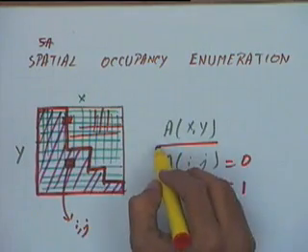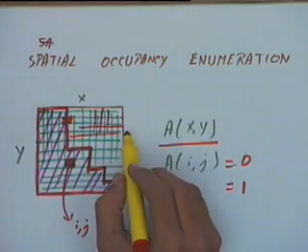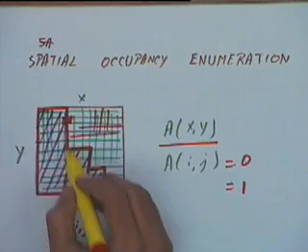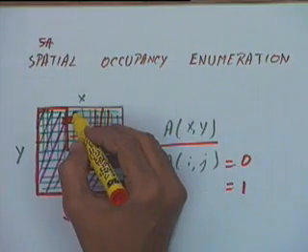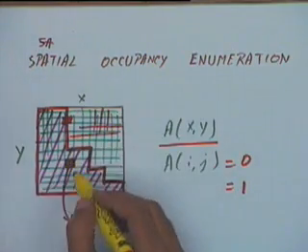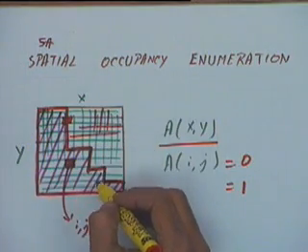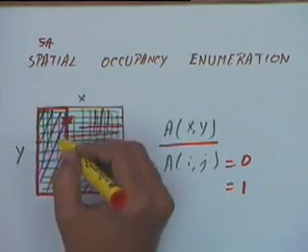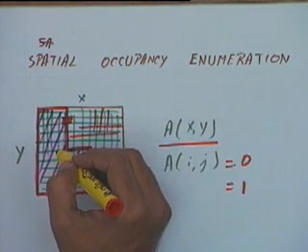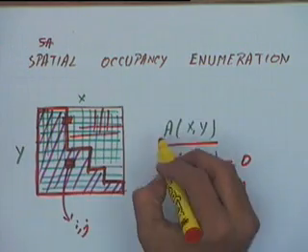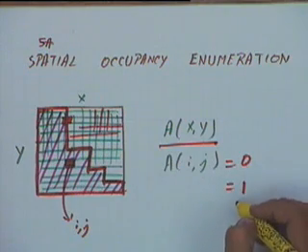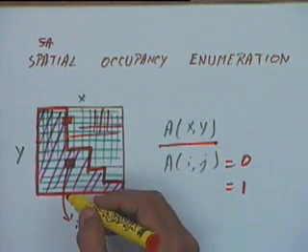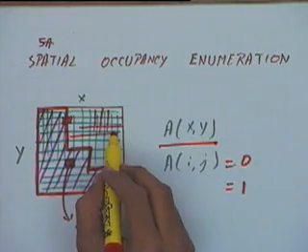Because if it is a uniform array, you like your squares to be uniform. If you want to have a non-uniform size of the square, that will obviously save some space for the area which is not there or the area which is totally inside. There you can have a large size, and then a small size at the boundary. But then you have to keep track of the size of every cell. We will see methods for doing that also. If I am just keeping a uniform array, and for every cell we say it is either a 0 or a 1 depending on whether it is outside or inside, then we like to have a uniform size of the cells.